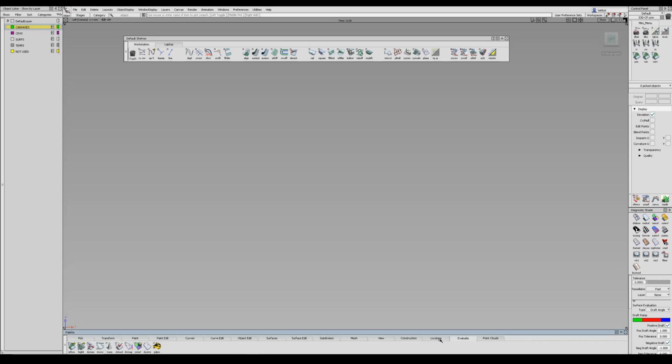These are deviation tools. So under locators, deviation, curve to curve, surface to surface, curve to surface. I use those all the time because I'm always building with gaps in mind or very precise positions of objects relative to each other. So I'm always analyzing those, so they're in a very dominant location on my shelf. Stitching, I constantly am stitching to check to make sure I have good quality surfaces and intersections. And when I send data off to CATIA or to NX or something, I'll want to make sure that it stitches within a specific tolerance. And then my normal, flipping normals for various tools and reasons.